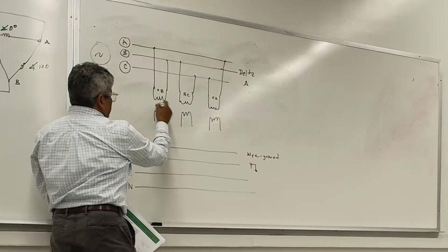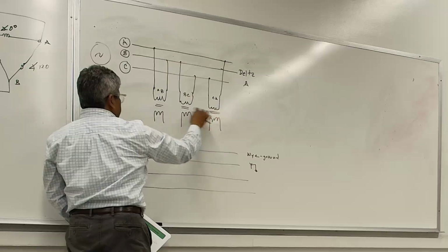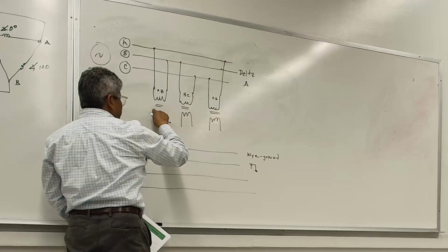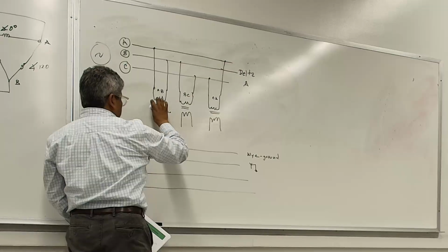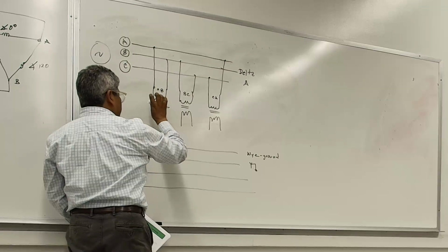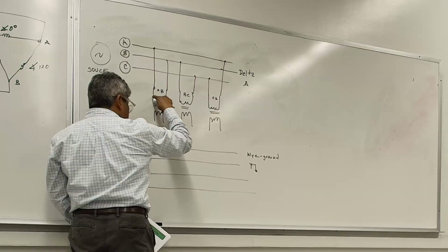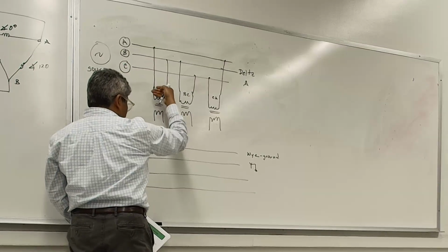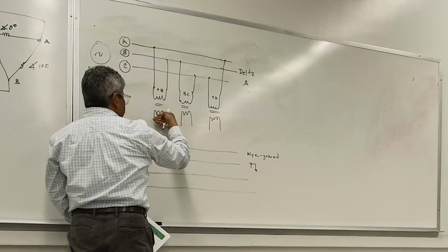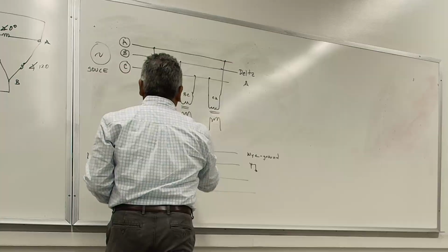And these two lines, by the way, if you see two lines, I think I mentioned this before, this means that the transformer is galvanically isolated: not physically connected but magnetically coupled. That means that there is no connection between this winding and this winding. The only way we can transfer energy from the primary to the secondary is through the magnetic field. And we talked about that.